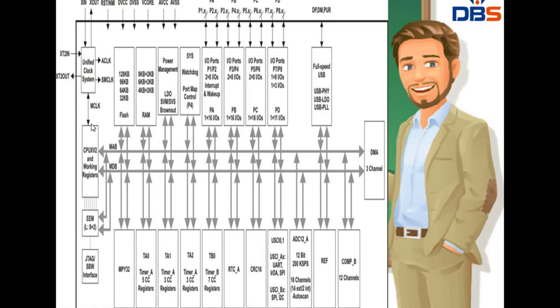These 3 clocks provide a clock frequency in order to run these devices. Here the UCS is providing 3 various clocks, which are SMCLK, ACLK and MCLK. Using these clock signals, the user can select the best balance of performance and lowest power consumption.